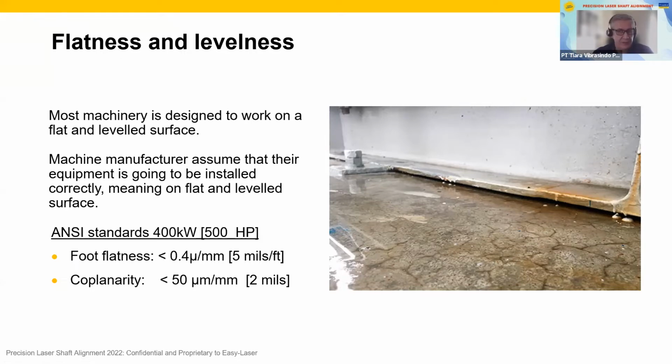When the bearing is squeezed, the lubrication film is forced out, and we will have metal-to-metal contact appearing. So excess heat is generated and your bearing is running into failure. That is quite simple. All other failures will be linked to this kind of stress. And it often starts with a flatness issue. Because if the foundation of a machine is not flat and leveled, you get those stress components inside of the machine and your bearings suffer from them.